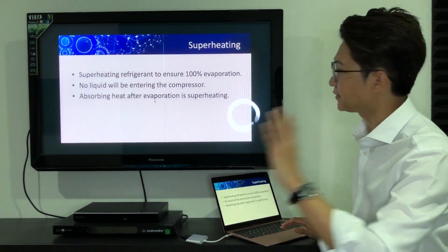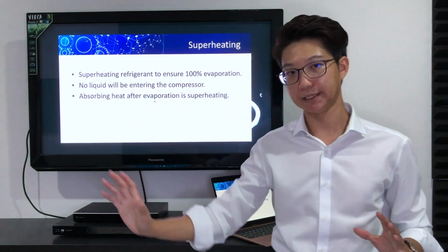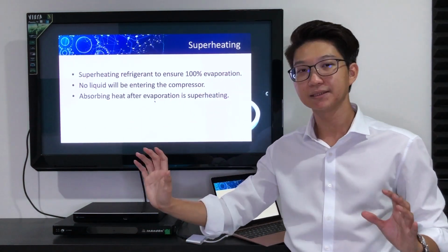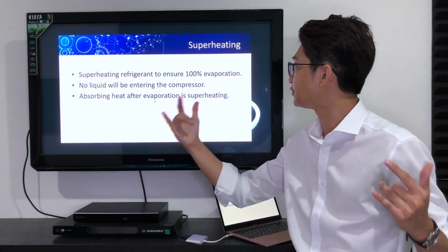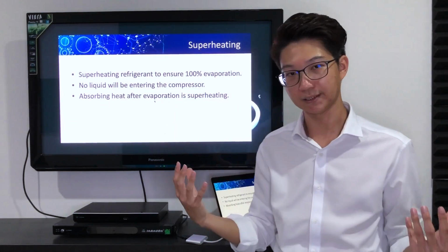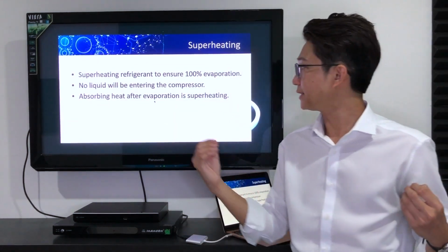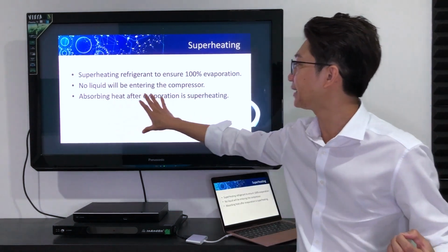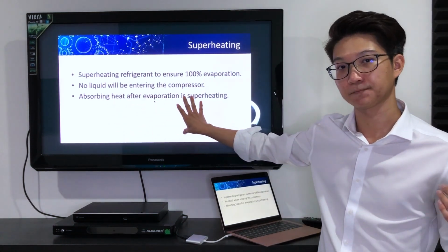So the first thing we use is the superheat, right? We use superheat to ensure 100% evaporation. Okay, what does it mean by superheat? Basically, superheat is absorbing heat after the evaporation process.